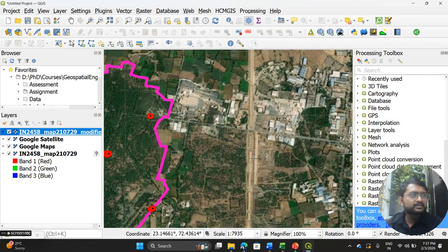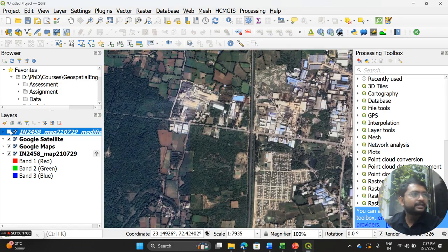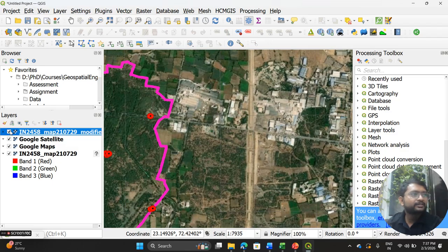in that you can see the construction of the road is still going on, and you can see a little bit here and there it is happening. It means this much error we are having. Okay, so basically you had one old image, and then you do the georeferencing, and then you compare it with the recent georeferenced data. This will happen most of the time in archaeology, where you go to the field, library, or some ancient sources. You will collect the data, scan the maps, and do the georeferencing. And then after, you apply the same thing. Same thing goes with the cadastral maps.